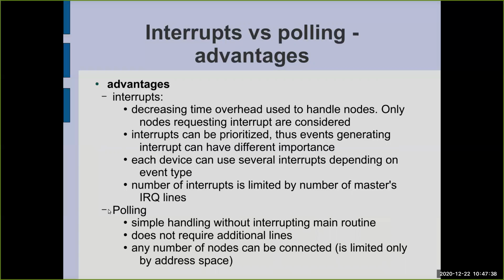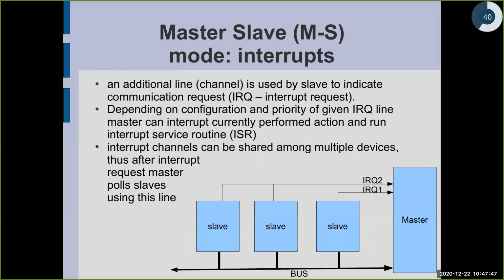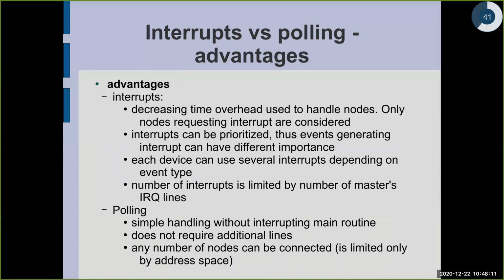But what are the benefits of polling? It's simpler than interrupts. You can imagine that master runs its own program, and asynchronously an interrupt is called. So it has to stop its work and switch to an interrupt service routine. So it makes the program much more complex.